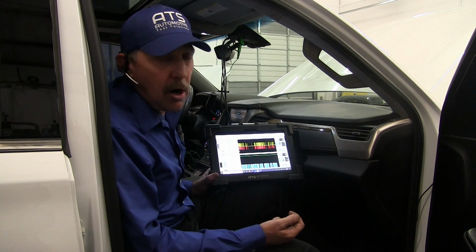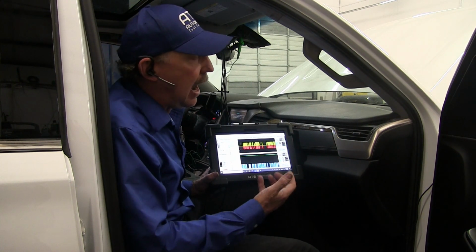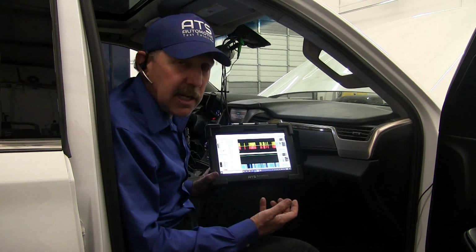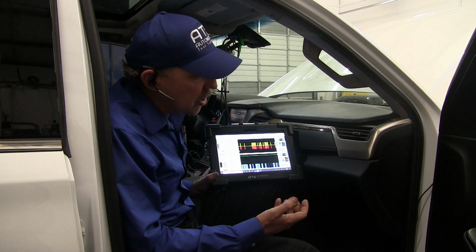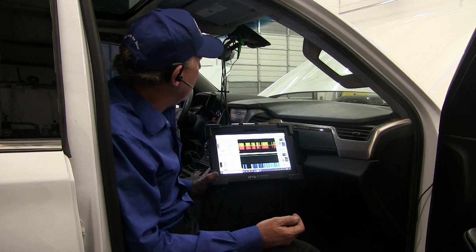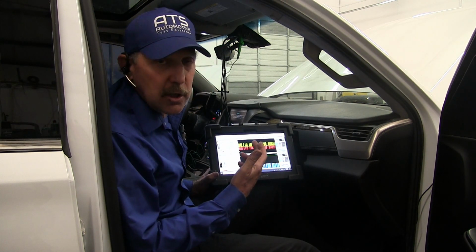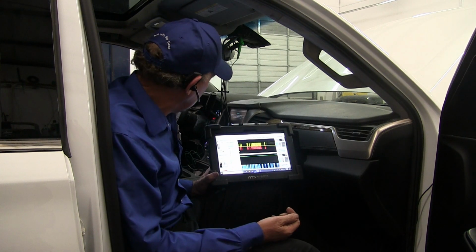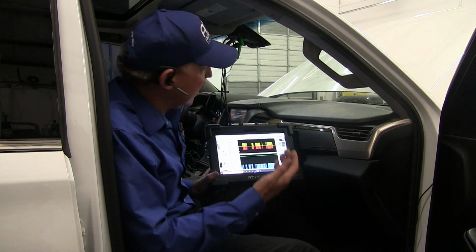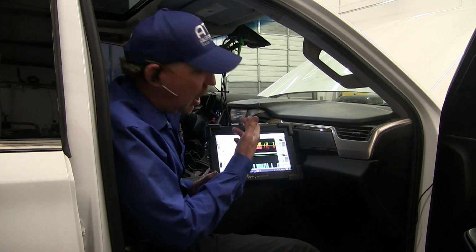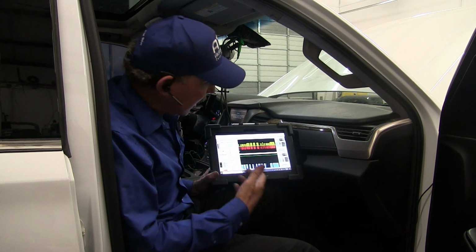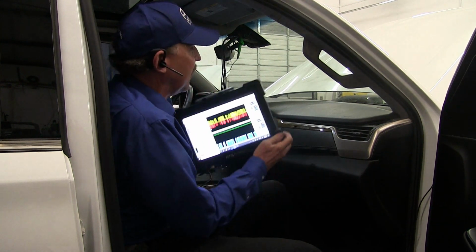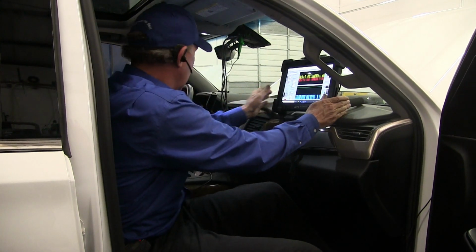I picked this car just so you guys can see how the wiring and a scan tool can really get you confused. But if you take a logical approach, it's pretty simple. So basically, this wire's been broken. That's what's going on with the car. Now the shop is going to need to repair the wire. All I did was bridge this outside.